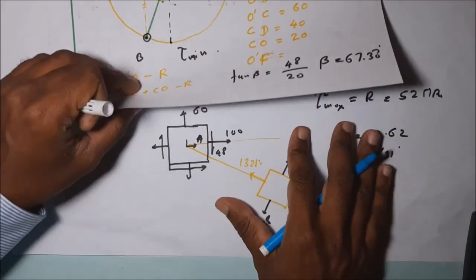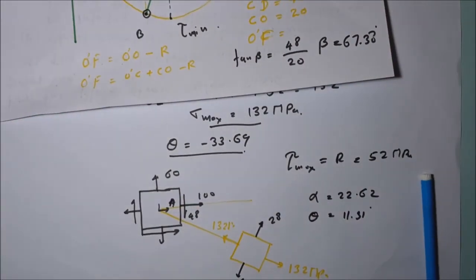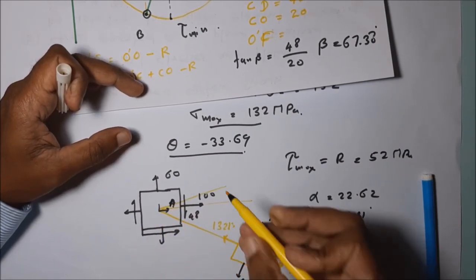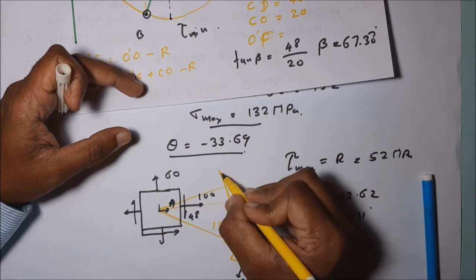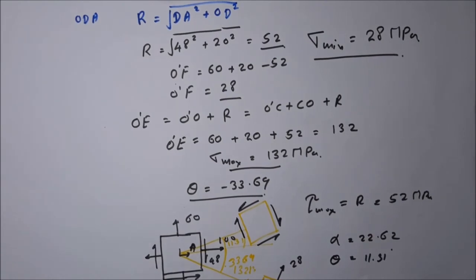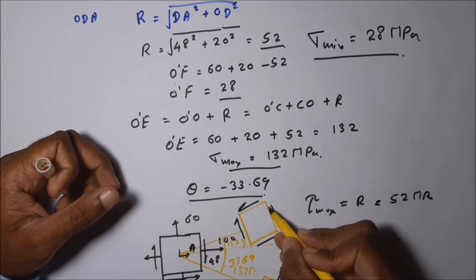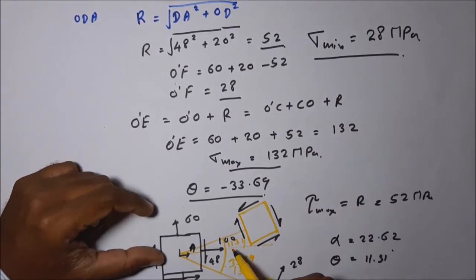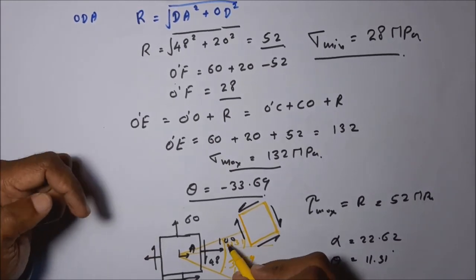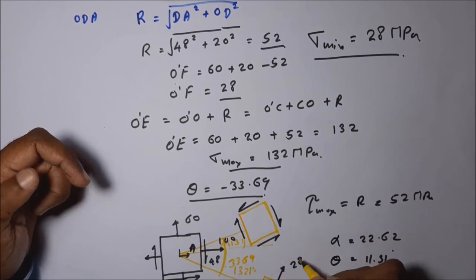Okay. Then in the same diagram we can represent the tau maximum point also, somewhere in this kind of direction with a small angle of 11 point something. In this direction, the shearing stress is maximized. We can mark the maximum shear stress in this way. The angle is 11.31. That means with the maximum principal stress plane, this angle is always 45 degree.